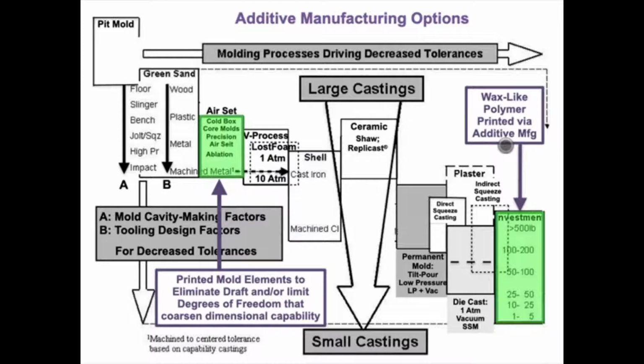Specific to the ceramic shell investment process, it is often not realized that the traditional aluminum tooling to form a wax pattern has a small draft offset if the draw length in the tool is very long. And wax contracts a little bit, like the pattern maker's contraction difficulty that we have with all the metal casting alloys. So in the case of the investment casting process, you have wax contraction to consider, as well as pattern maker's contraction to consider in the alloy itself.